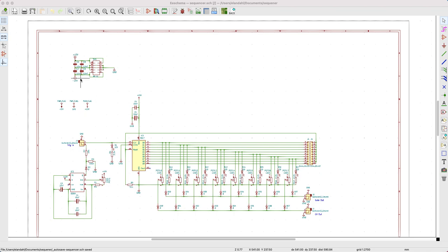The way this works is that on the power connector, as usual, we have plus and minus 12 and ground. We have some capacitors for filtering, and then these symbols which indicate this is a plus 15 volt and minus 15 volt and ground source, and then these flags are identified to be used throughout the rest of the diagram.